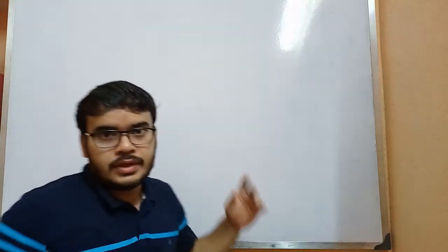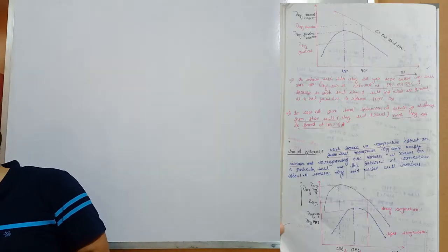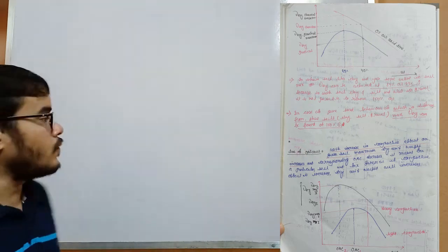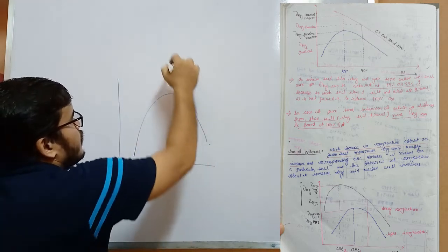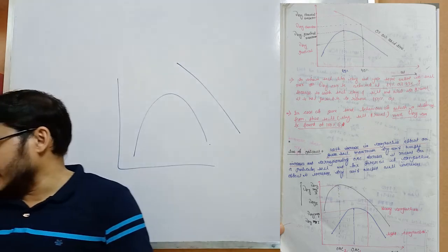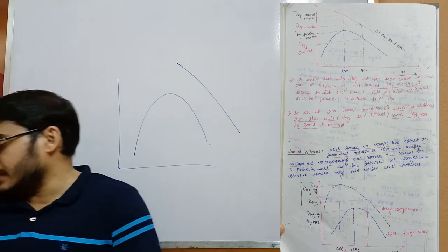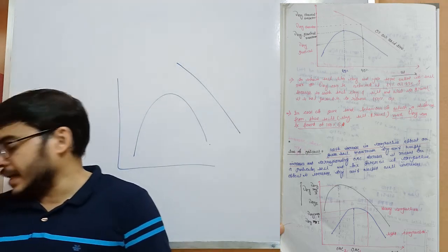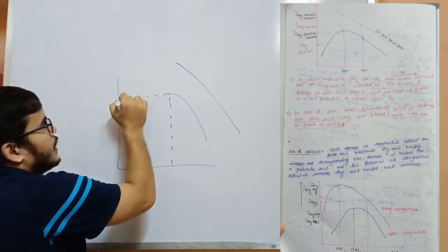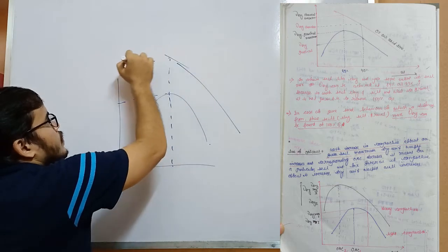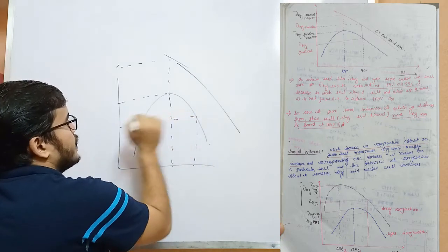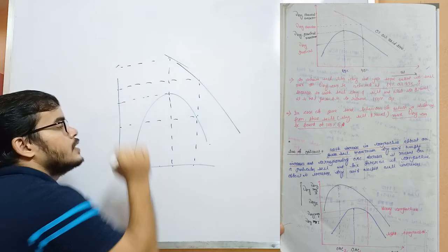And now write down the note here and draw this graph. You can easily understand the graph now, that two things are given. One is the practical gamma dry value, and one is the theoretical gamma dry value. Here this is the value of practical maximum gamma dry, and here this is the value of theoretical maximum gamma dry, and for this water content, this is the value of practical and this is the value of theoretical gamma dry value.